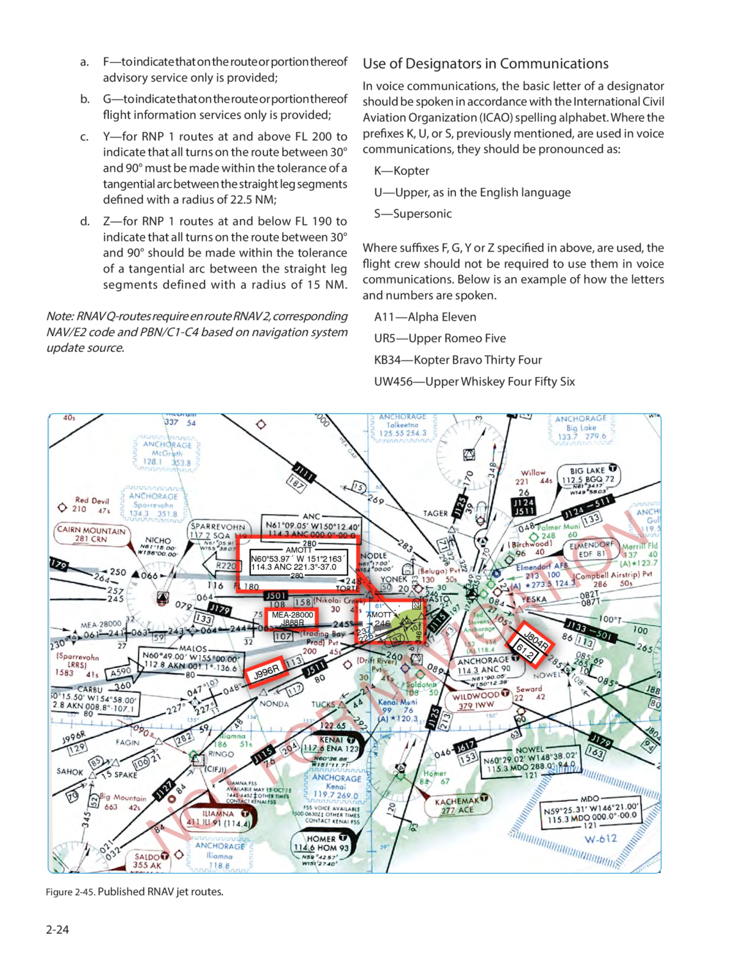Note, RNP routes require on-route RNP 2, corresponding NAV/E2 code and PBN/C1-C4 based on navigation system update source. Use of designators in communications.